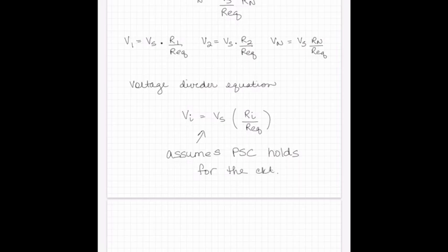So that means that the current is flowing from plus to minus through the resistors, that the source is delivering power, all that sort of important stuff according with passive sign convention, okay? So if it's not, we're going to have to change the sign on the source voltage to make it happen. Just like we would for Ohm's law, okay? Because really we're changing the sign on the current, which is right here.